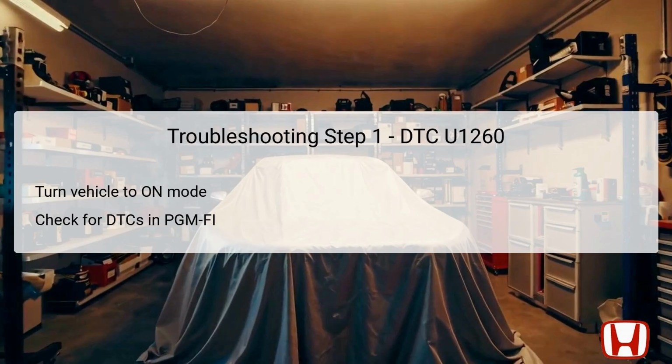The first step in troubleshooting the U1260 DTC involves turning the vehicle's ignition to the on mode. This allows systems to power up without engaging the engine, providing a baseline for checking electronic systems. Next, utilize the Honda Diagnostic System, HDS, to scan for any pending or confirmed diagnostic trouble codes within the Powertrain Control Module, PCM, or Powertrain Control Unit, PGM-FI system.